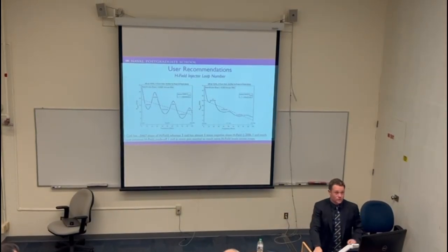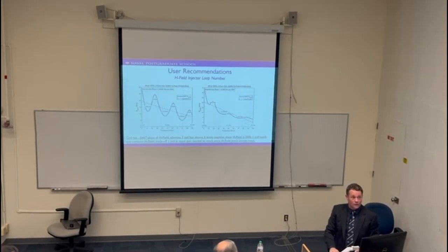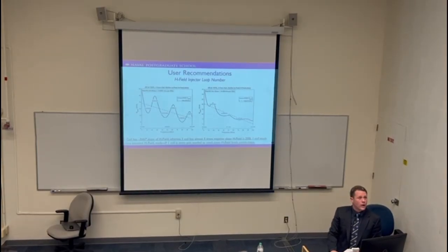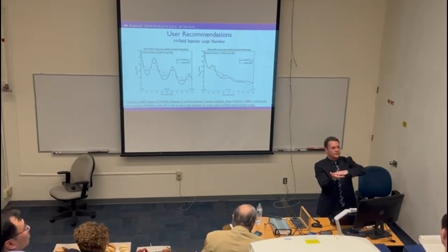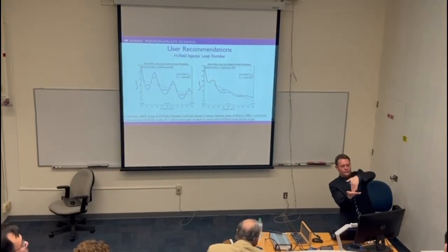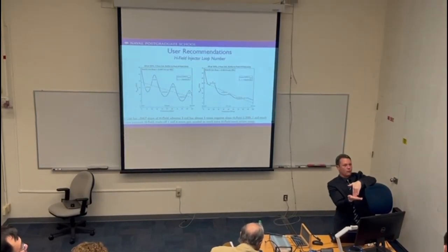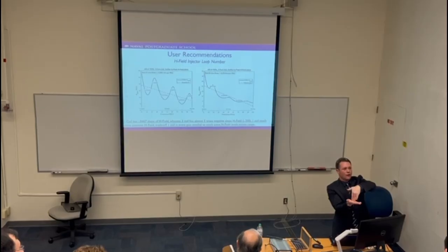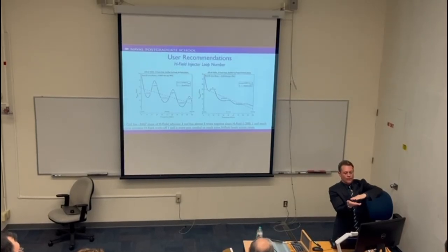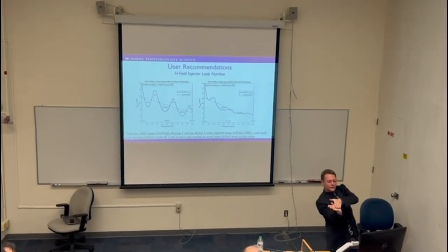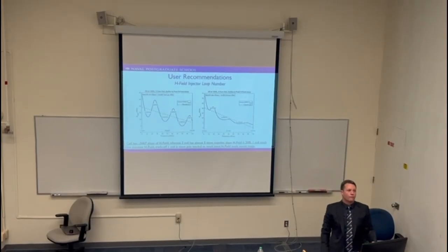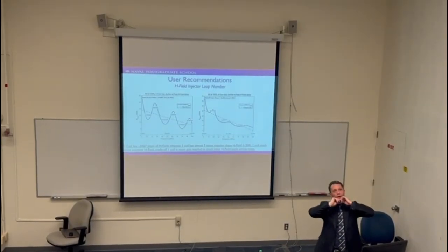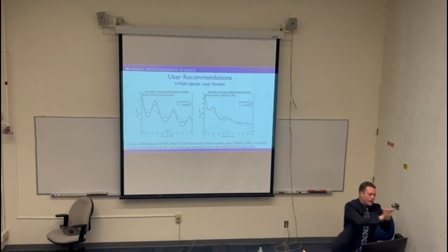Rob, actually, let's go back to your orientation of your sniffer. Does that have anything to do with it? Oh yeah, I mean obviously, yeah. If I'm not getting the same flux through it, if I come off with the sniffer at an orthogonal angle to it, I'm going to get much less. Rotation around it is noticed, but certainly as I come off angles, you're dropping off quite a bit. But again, I'm trying to simulate the scenario where I'm right up on the EUT.